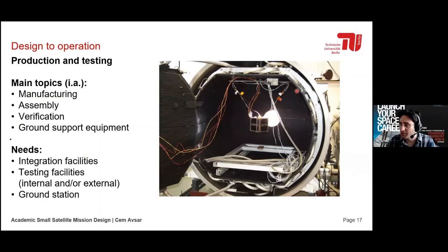So the walls are cryogenically cooled down to below -100 degrees centigrade, to simulate the space environment. You see a light source, which simulates the heat from the sun. And then the satellite hangs here, and then the air is pumped out, so you have vacuum inside, because you don't have convection in space, you only have radiation and conduction. So you simulate the space environment, and check if the equipment of the satellite stays within the boundary temperature conditions.